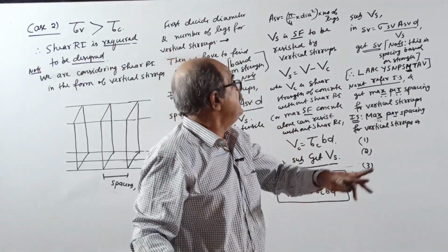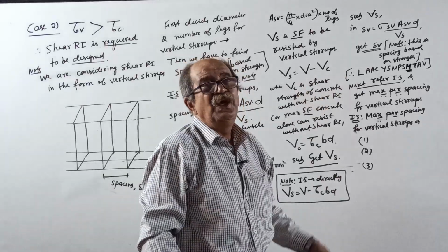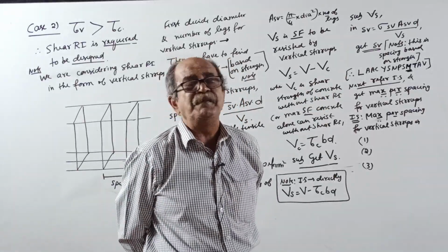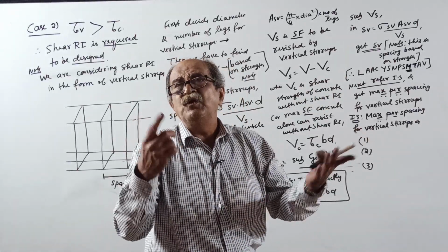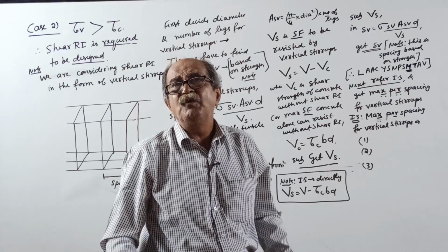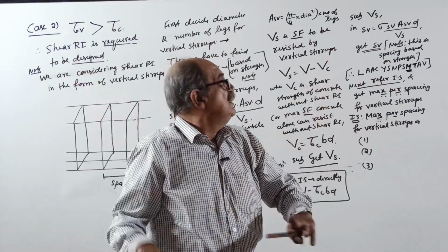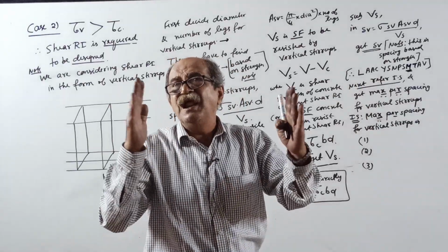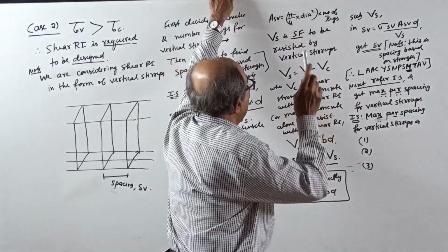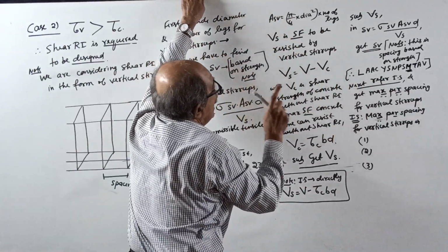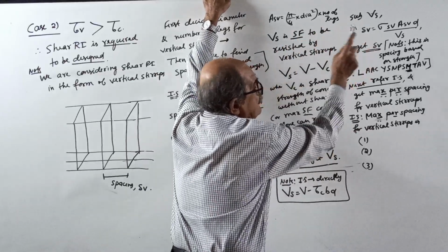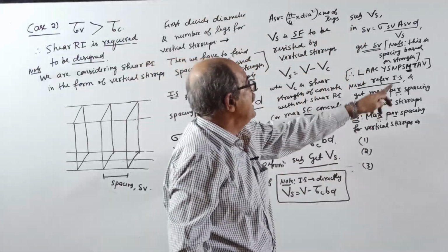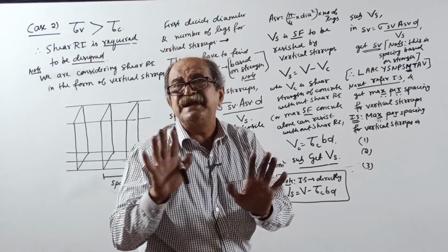Suppose the spacing comes to, for example, 118.5 mm. You make it 125, the beam becomes weaker. Why? Stirrups are going away. You make it 100, good, stirrups come closer. So at any cost, you should not provide spacing more than this value. I first wrote less only to make you understand.